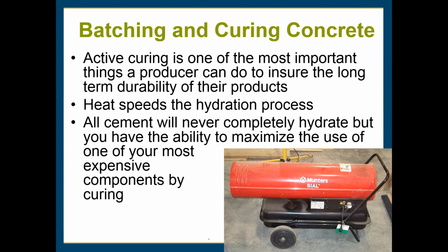So again, active curing is extremely important. You could have the most perfect mix design on paper, but if you just chuck it outside in the sun and the wind and try to let it cure that way, it's just going to be a disaster and you're going to ruin it. So curing is extremely important. Every step of the process is.